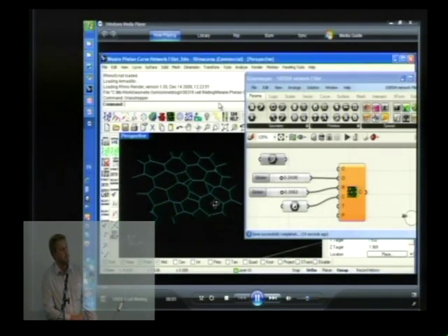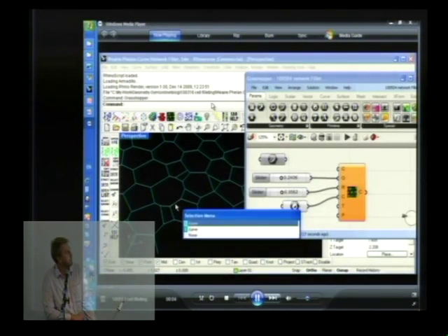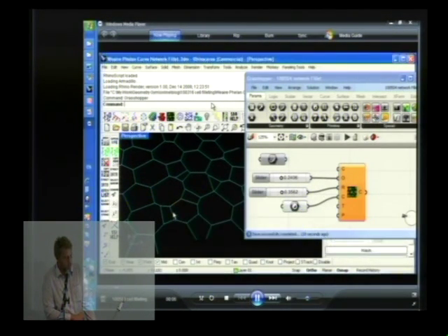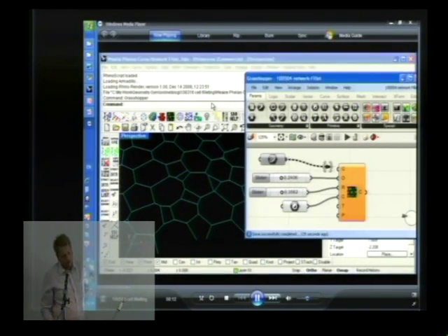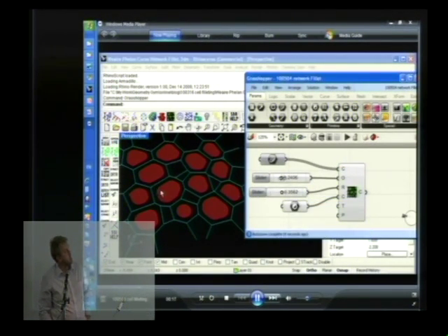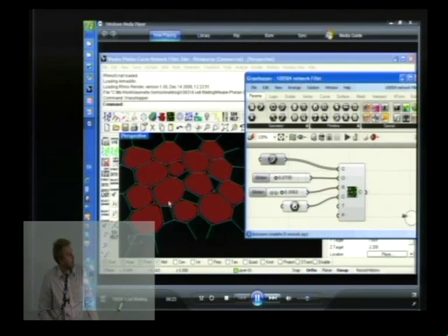Voronoi diagrams have been quite popular in architecture, which is similarly related to the Water Cube. But it was the Weaire-Phelan polygon pack. I've done a couple of other routines because you can do Voronoi and produce the cells by the polygons formed by that diagram. But this one actually works on any curved network without necessarily having identified the closed boundary of the polygon. So these are all just single curves forming this network, and basically the routine identifies the curves, works out the perimeter, and works out the voids in that area, and then gives you options for generating the cell.